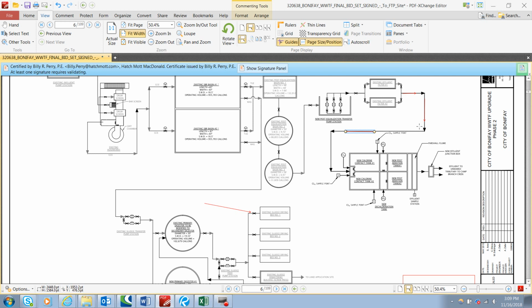Now this is not a scaled drawing. This is a symbolic drawing. And there's a big difference between the two, and I want you to understand what this means. This is a simplification of the entire plan set. This plan set, if you look right here, is 109 sheets to it. This simplifies the whole set into one diagram, and it's easier for the reader to understand than to try to go through 109 sheets and figure out what in the world we're trying to do.